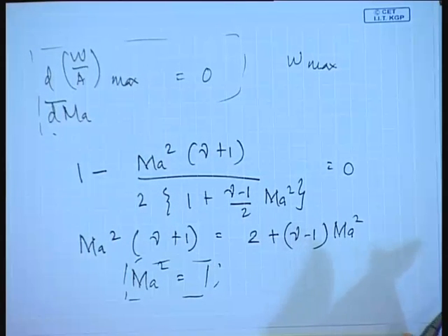So, therefore, we were talking about the choked flow conditions, or rather we were talking about dA equals to 0; when dA equals to 0, MA equals to 1, and so on. We find why MA equal to 1 is so very important, because that gives us the maximum flow rate from the converging nozzle under the present circumstances.